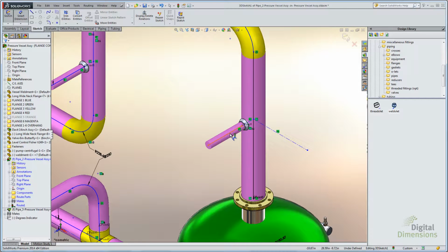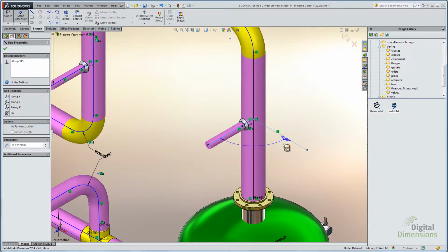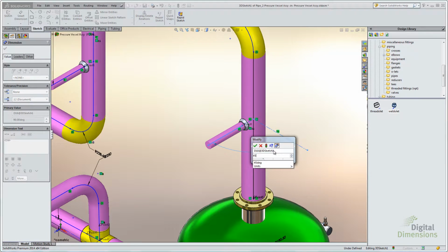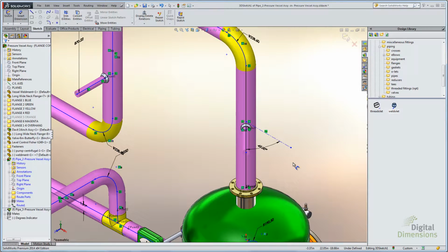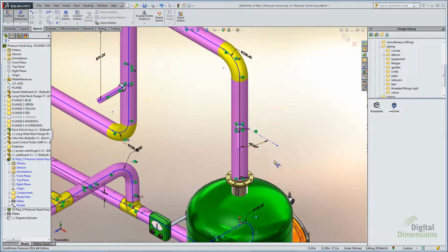So here I'm going to use this center line to help me put this at a different angle. So you can dimension linearly and angularly with the dimensioning scheme, and it is just a lot more user friendly than it was before. So weld OLET and thread OLET, you'll like some of the dimensioning functionality that's been added. It's a little bit easier to manage.